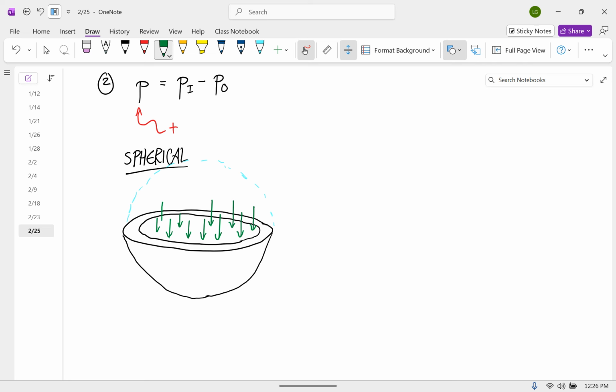And that is applying a total force F. And then as long as this thing is withstanding the pressure, that has to be counteracted by pulling forces applied to the metal in our chosen part by the metal on the outside, the adjacent metal of the pressure vessel that's not in our chosen body.